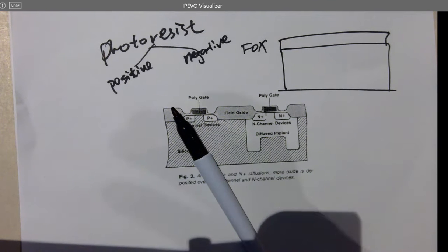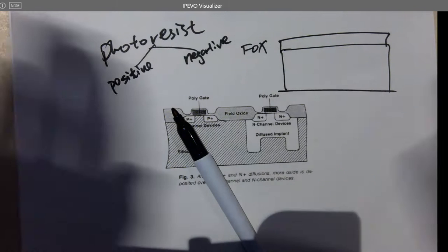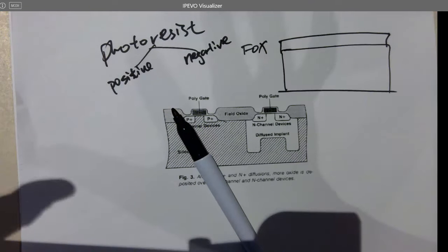Clean room is the place you can fabricate integrated circuits. Usually it's 1 cubic meter in the clean room. It has 100 level or 1,000 level, which means 100 level is 1 cubic meter has 100 dust particles. And the 1,000 level is 1 cubic meter has 1,000 dust particles. You're wondering how many dust particles we have here in the classroom? 10 billion, right? So it's super clean. And with the orange light, it's not damaging the photoresist.